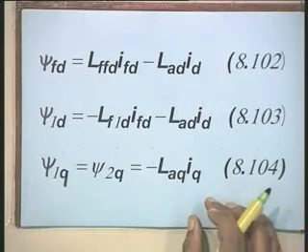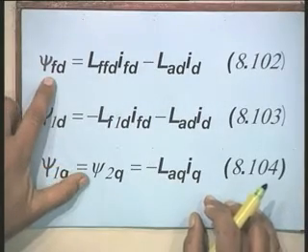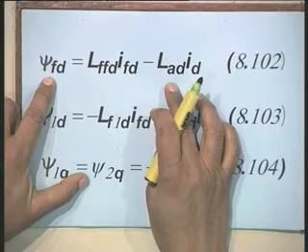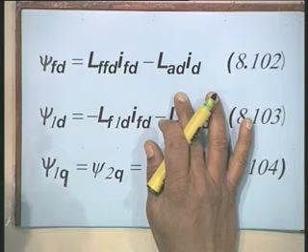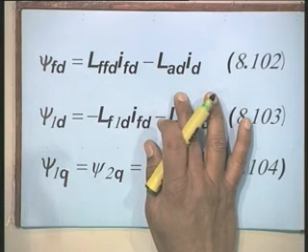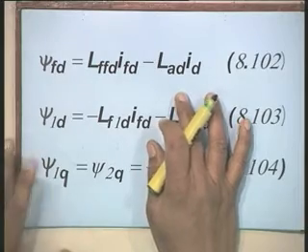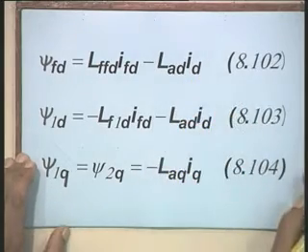Another thing, while writing here, we have also said the per unit mutual inductances on the d axis windings are equal, right. Therefore, you will find here that when you write psi d, it is L A D I F D, and when you write psi f d, again I have put L A D, because the mutual inductance between the stator d axis winding and the field winding has been made equal in the per unit system. Therefore, this simply appears as LAD.